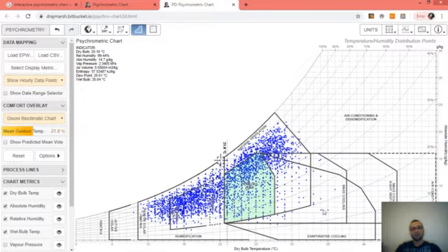There are some locations, and we have seen case studies. For example, in Sydney, Australia, we have seen a building where they have used thermal mass, and between 1 to 5 a.m. in the night, the temperature drops and night cooling could be used. So there's fluctuation between day and night temperatures.